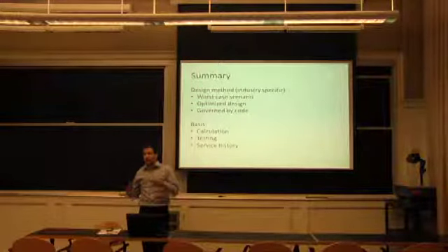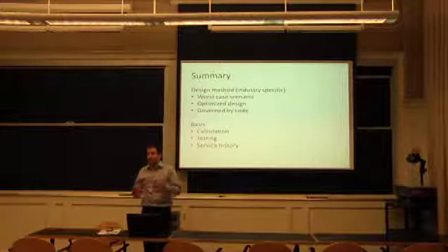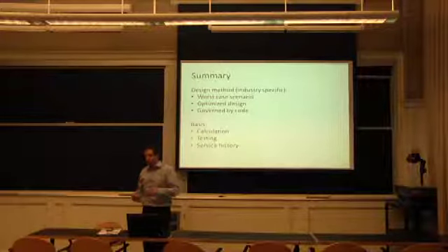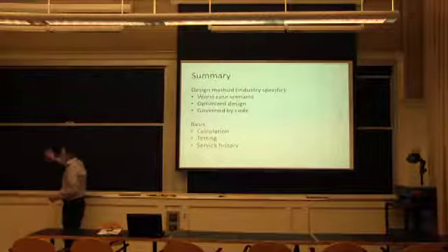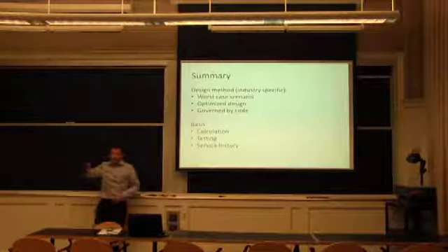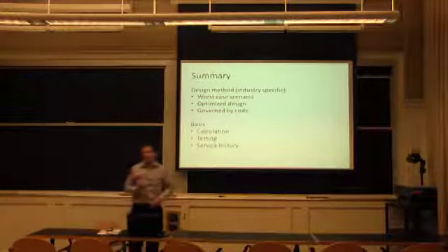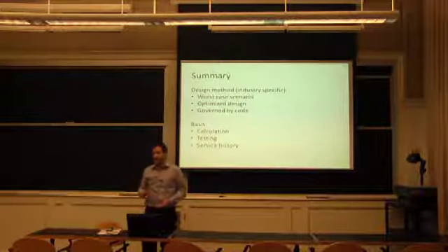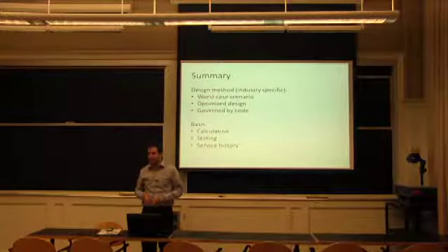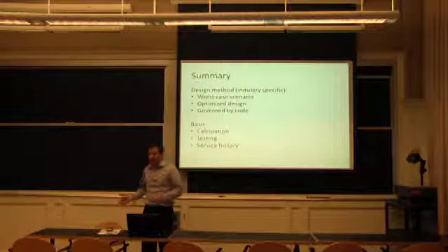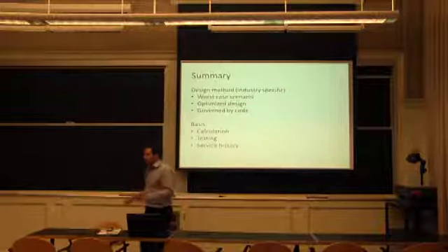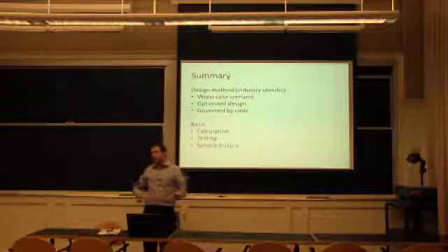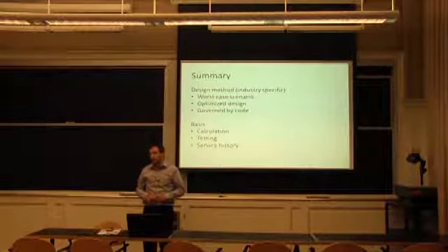But how much you can modify it becomes the question, because you still don't have all the groundwork on where you stand with respect to demand and capacity. Are you too good or just exactly where you should be? That requires analysis. It's doable with those statistics things that we talked about and looking at other designs. But it's not something you can say, oh yeah, we know it's designed with a safety factor of 3 and we never had a failure, so we're going to add 20% load.